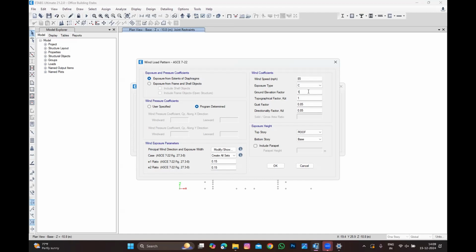They will connect to the system, with wires on top of the ground. They will see the shear wave velocity, whether there is any cavity, any liquefaction. It is not about the chemical properties. In the other one, you take a sample to the lab and test it, which gives the chemical properties, and you do the SPT test. But geophysical is checking the shear wave velocity and such things. You get the point. When the shear wave velocity is low, it is called liquefaction. You know liquefaction, right? I already told you.